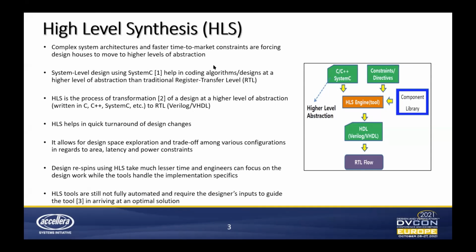SystemC combines the best features of the object-oriented C++ language along with hardware description constructs, thereby making it well suited to describe designs at a higher level of abstraction. HLS is the process of transformation of a design at a higher level of abstraction, typically written in either C, C++, or SystemC, to RTL, which is nothing but your Verilog or VHDL design.